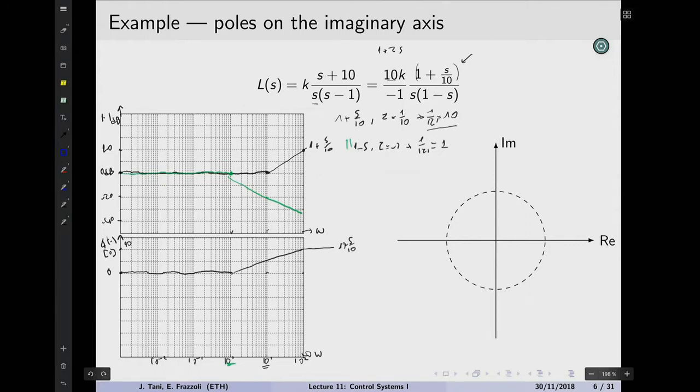Well, the phase, now this is a little bit, try not to get confused. So the phase is something that starts from 0 and ends up at pi half, 90 degrees. It's at the denominator, so it's actually minus 90 degrees, but the tau is negative, so we flip it over again, it's plus 90 degrees.